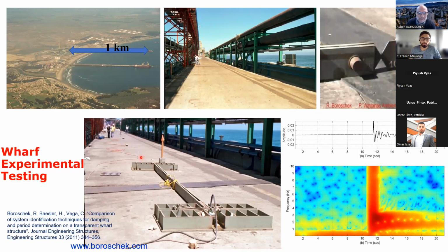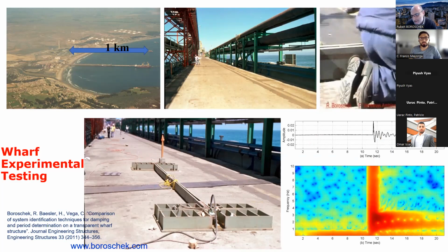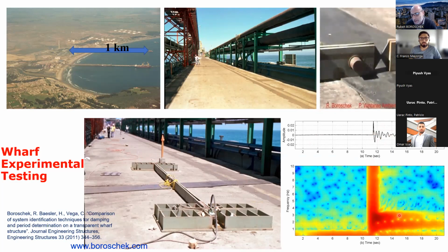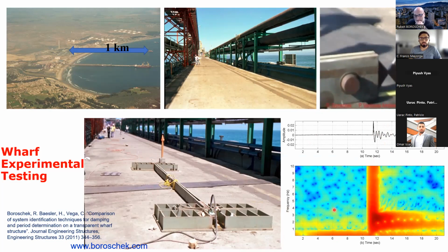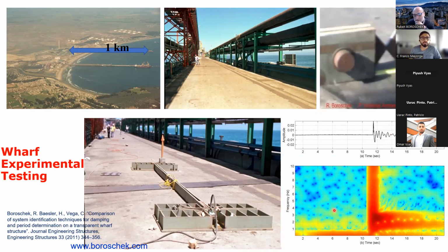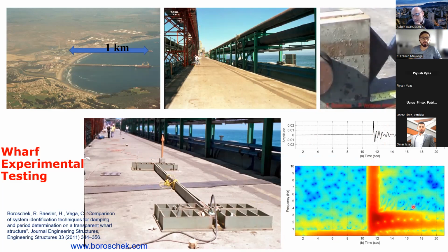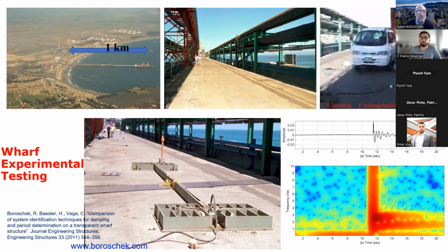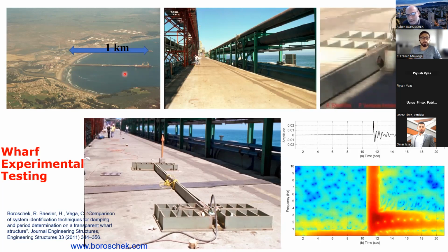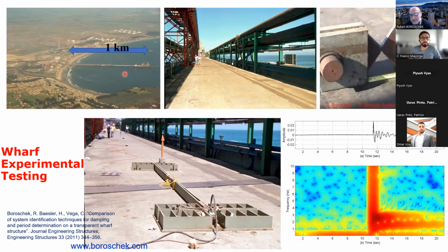We have velocity sensors, accelerometers, deformation sensors, everything. We got the analysis of the signal. We do different type of analysis. This is a problem of initial condition with multiple mode shapes. In this case, you're seeing a time frequency decomposition. Very simple one could be a short time Fourier transform or more sophisticated tools. And we just get from this decay mode shapes and damping, and we were able to tell the owners of this port that the damping was below 3%, and they went into spend more than $10 million in retrofit. It was starting the 2000 or something like that.